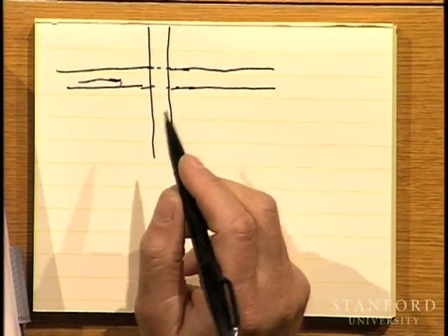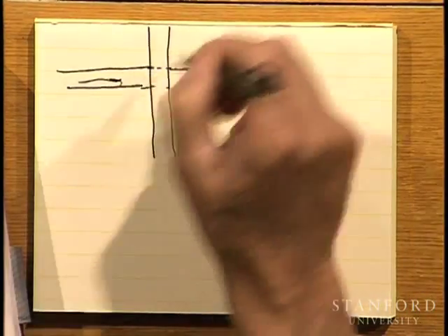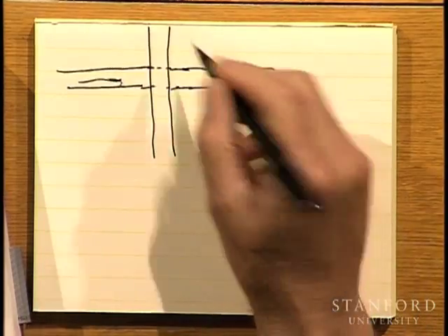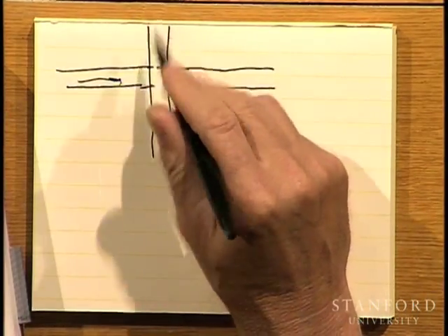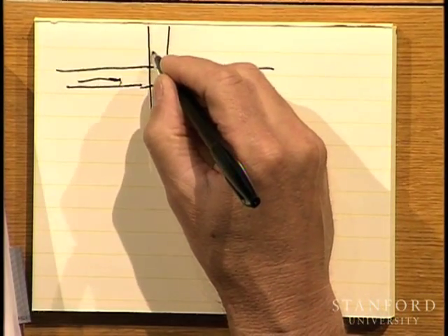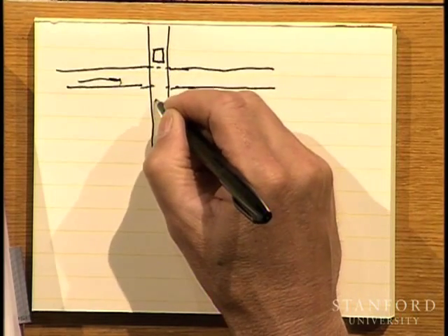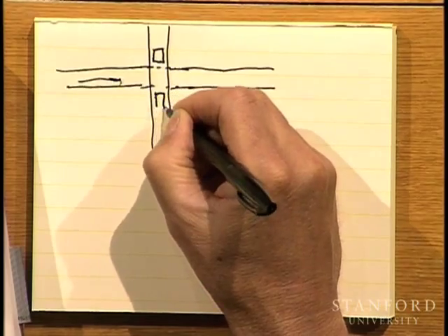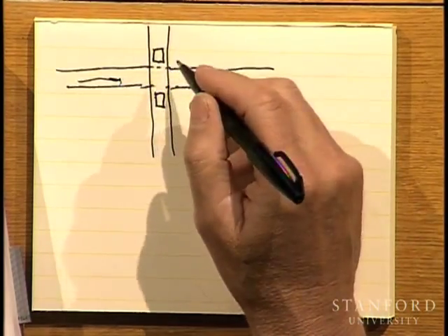In our multi-step imprint lithography process, the way we do that is we first pattern this cross with all the layers. So now we have a cross on the top and a cross on the bottom, and that's not very useful. The additional trick we do is we put a little hole in the areas where I want to actually create this crossover.